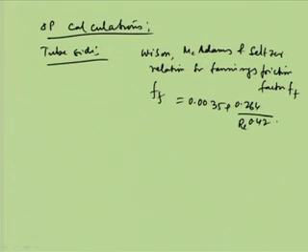Now, in case of the tube side, we have seen that for delta PF, using this Fanning's friction factor, we get FF equal to 0.0087 and FD as 0.0348, 4 times FF.